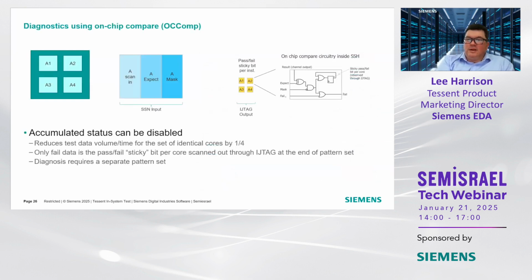I mentioned diagnostics. There are several levels of diagnostics you can do with the in-system test controller. It is possible to do full detailed diagnostics as you would do on an ATE, but also typically used is the less granular diagnostics, which is essentially looking at the various cores within the design.